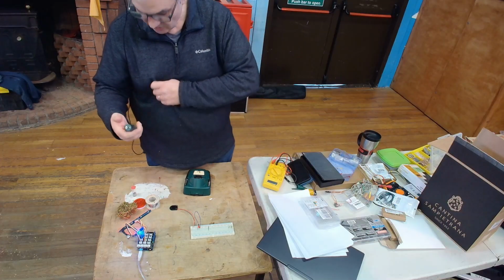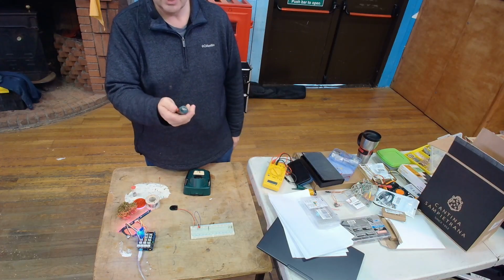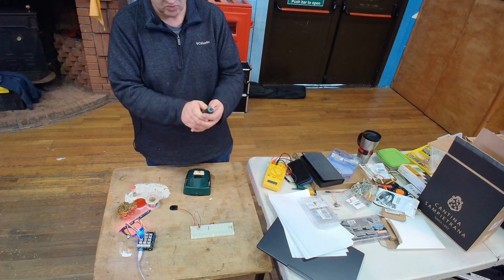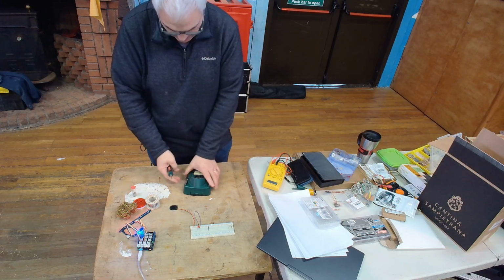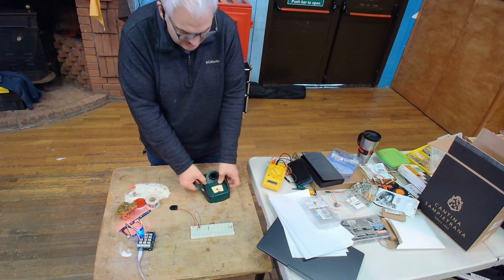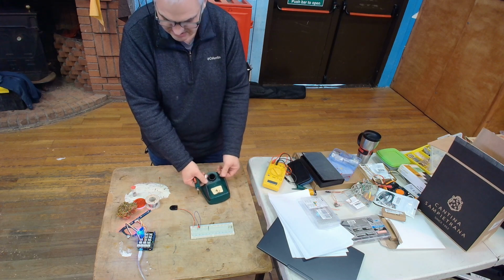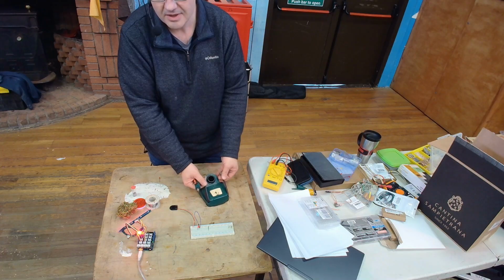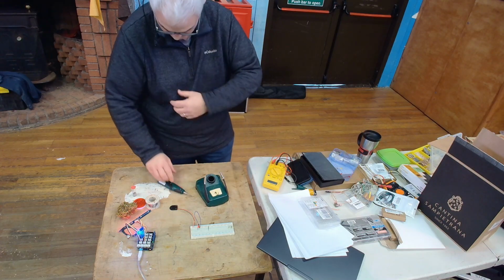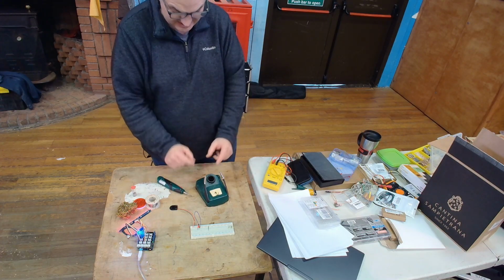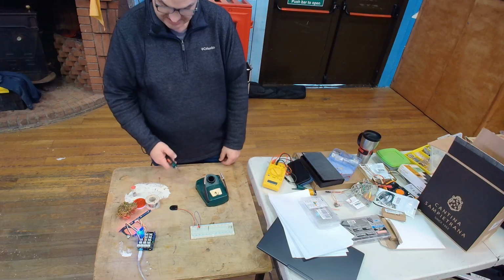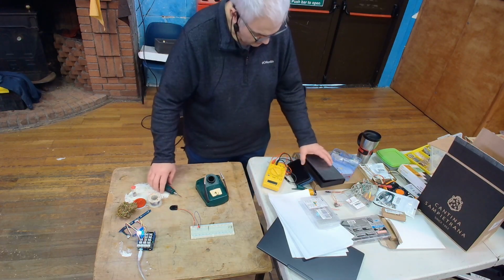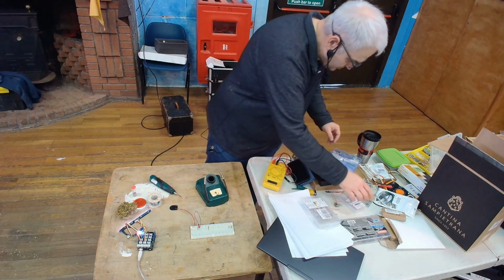You get soldering irons for next to nothing. I think that might cost me 10 and little. It's a little battery powered one. So something you do need if you're soldering is either 3 hands or some sort of clamp, because you need to hold the wire, but you also need to hold the soldering iron and the solder.